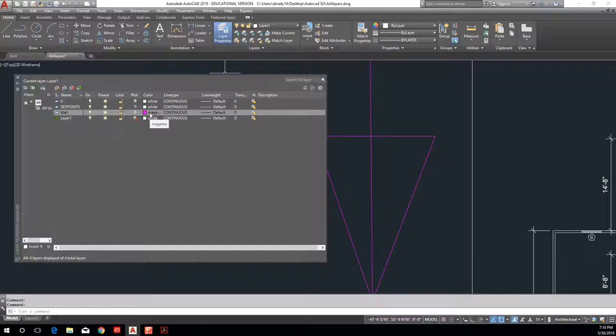But AutoCAD doesn't necessarily associate a thin pen weight with that, because so many different professions are using this, it wants you to tell it what magenta means. So it remains very generic so that you can customize it for whatever you're doing with your business. Magenta just means a color to AutoCAD, all right? We have to input instruction on what magenta actually means in order for AutoCAD to print it with a thin pen weight or a thick pen weight or whatever you have it defined as.